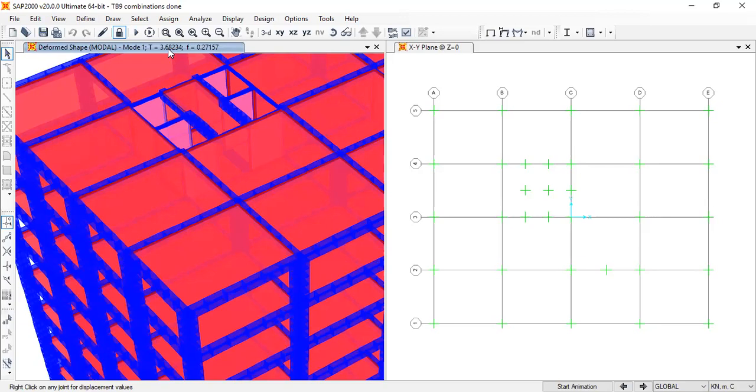So you should be able to interpret these results using your knowledge in structural dynamics, right? So omega is root K over M. So we increased the mass. Now we have the most accurate mass of the building, right? We increased M, but not the stiffness. So what then happened was we decreased the natural frequency omega, and T equals 2π over omega. So it will increase the period. So it is 3.68 now, right?